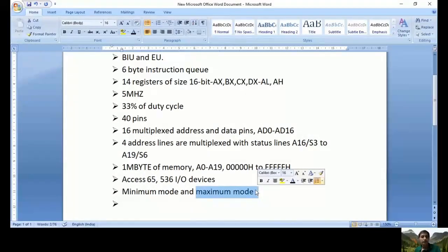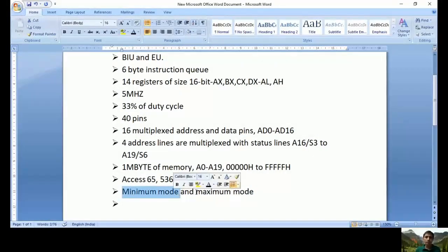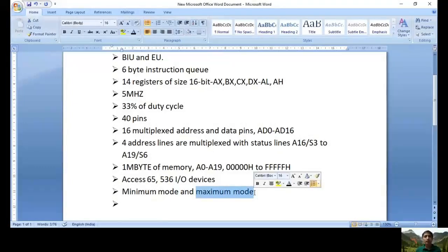With the help of that IC, the 8086 generates separate address and data lines. Simply, in maximum mode the 8086 gives a command to the external bus controller, and the external bus controller activates the transceivers and latches. Accordingly, it separates the multiplexed address and data lines into pure address lines. In minimum mode, the entire work is taken care of by the processor only, whereas in maximum mode, the activation is controlled by the external bus controller, but the command is given by the processor.